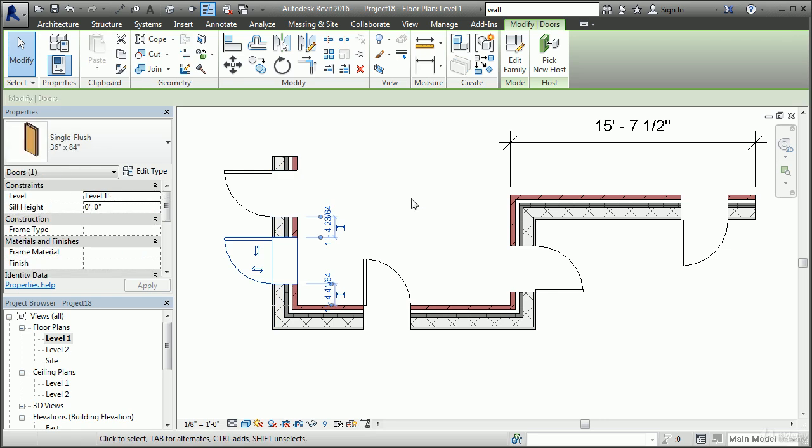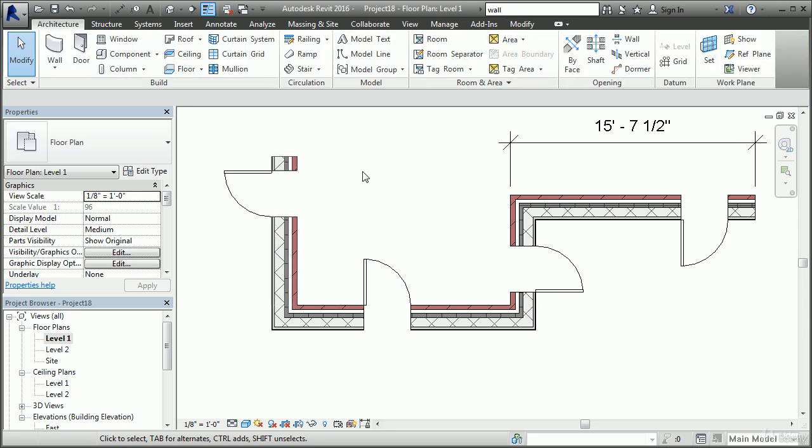If I want to start adding to the selection again, then I just let go of Shift, and I will be adding elements. To get rid of an element, you can pick it and hit the Delete key. There's also a delete option on the ribbon. Easiest way is to just use the Delete key.